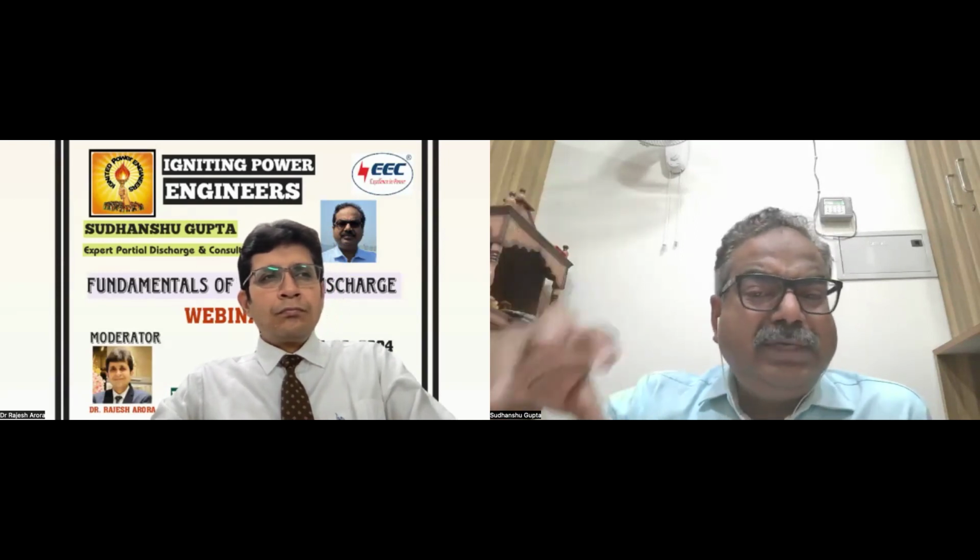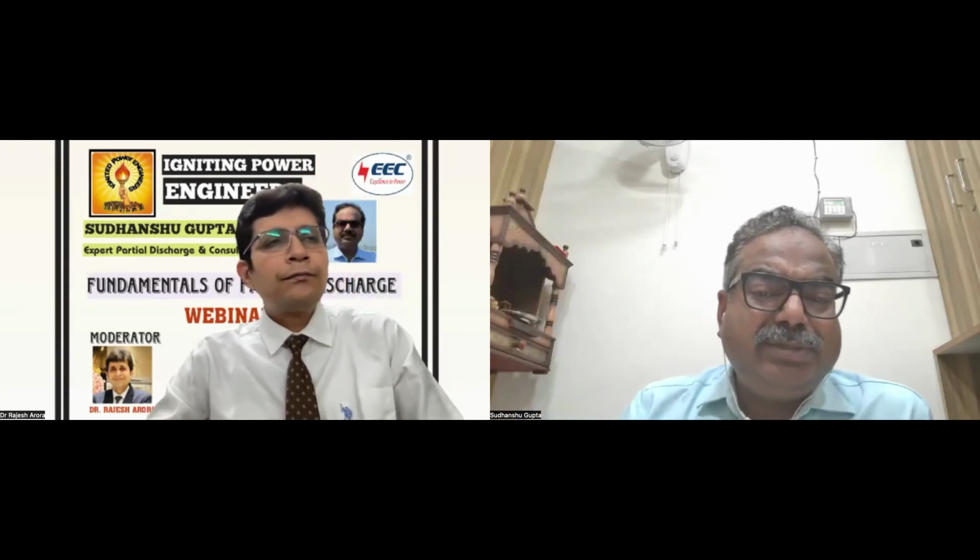Then they did some jugaad. They took it from the measurement circuit, from some coil in between. I would say this is nothing but a transformer. They just provided a transformer, and then he was able to synchronize, and we got a beautiful PRPD pattern of a floating component. So synchronization is very important, and PRPS and PRPD, I would say both patterns are very important for testing.